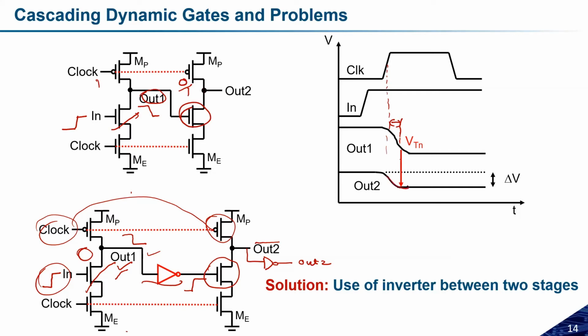So this is the degradation due to this. To avoid that, this transistor should not get the input immediately, because we connected the clock at the same time. We have added some delay so that it can change the logic, and the glitch should not be reflected, and this drop will be reduced. Okay, did you get the thing, or do I need to explain it again?